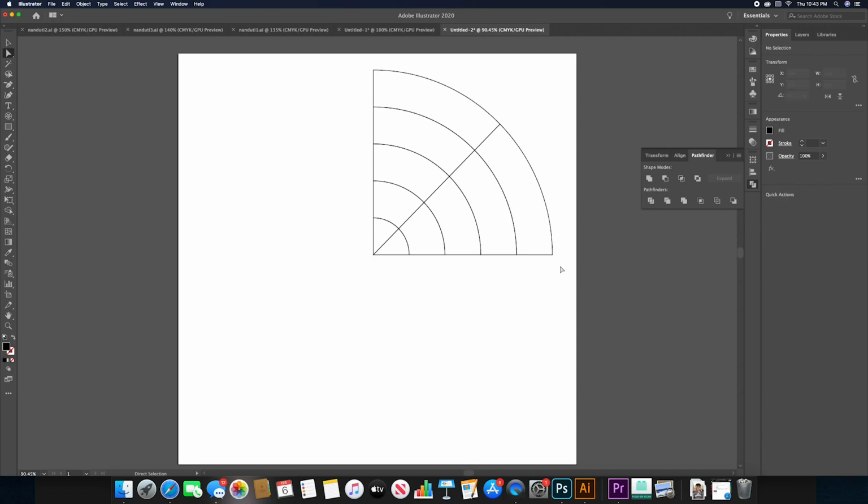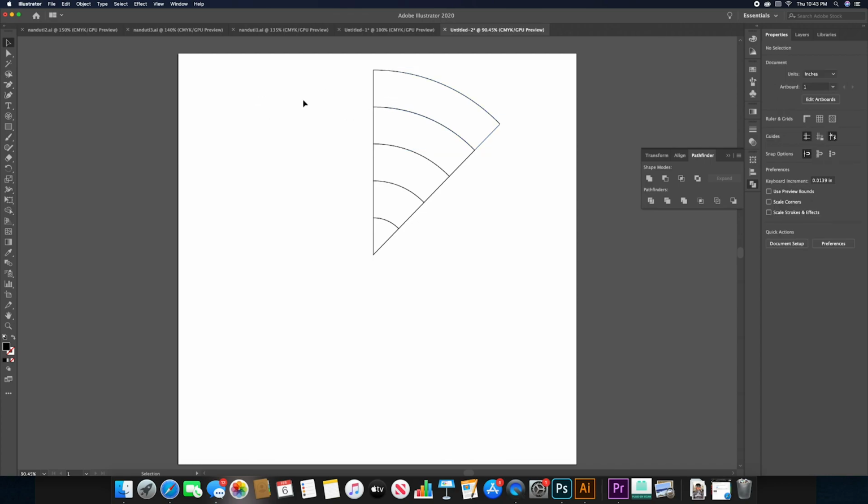And finally, I'm going to look to delete out the bottom half of this piece of the pie. So I'm going to click and drag over the anchor points that intersect. You can see that they highlight, showing the different anchors if I move my cursor over top. I'm going to hit delete or backspace again. We're going to still see a little hanger of an anchor point settled towards the top right. I want to click and drag over that specific anchor point and again hit delete. So we're left with one piece of the pie.